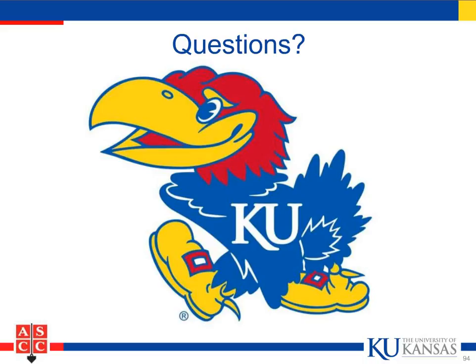Is this Tom? Is that right? This is Tom Ralston. Okay. Yeah. Okay, Tom. Great question. That sounds like you're using a lot of the technology that's out there right now. It's 2 inches. You're kind of right on the edge there, but you're using superplasticizer. You're using shrinkage reducing admixtures. You're minimizing the rate of evaporation. That's one point I want to get back to.